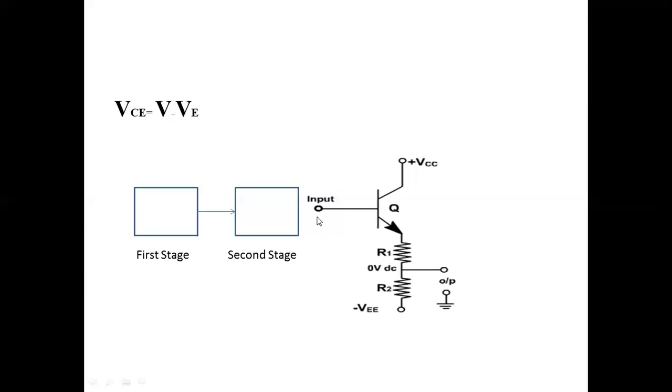That means instead of a 0 volt, your reference level is going to be shifted. That is maybe the same voltage available at the base of the transistor, and now due to the emitter follower circuit, that same voltage is available at the emitter. That means the emitter voltage in this situation is greater than that of an ideal situation.